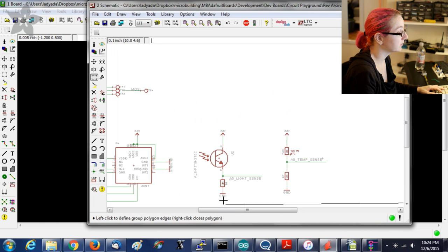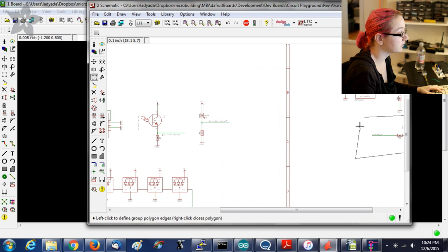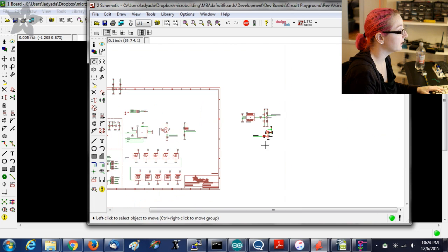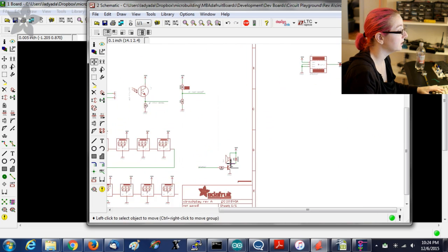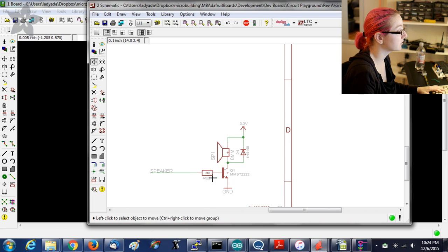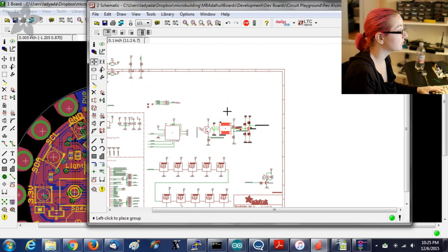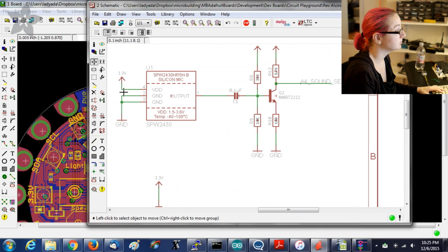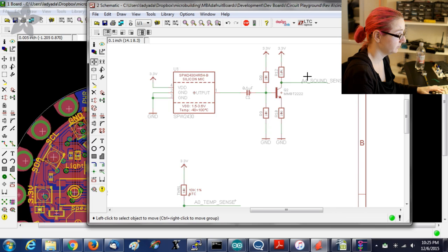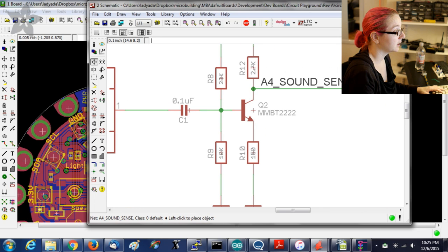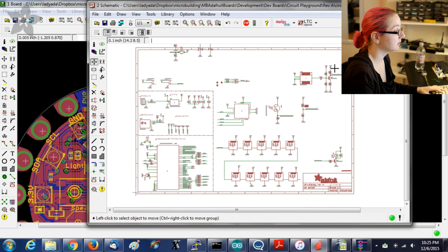Then on the last two items, this is that speaker that we did a while ago. It's just going to be a buzzer, square wave in, square wave out. And then finally the microphone, which is just going to give us audio volume. So a MEMS mic output, a little amplification, also into an analog pin.